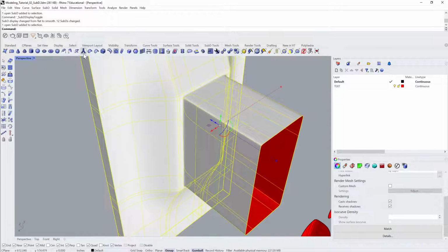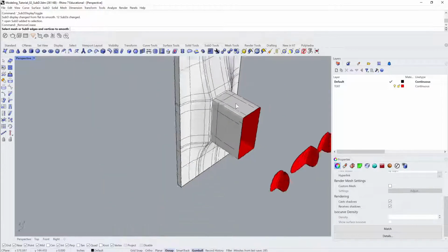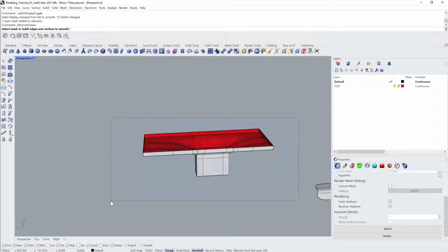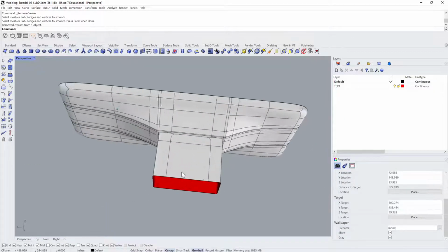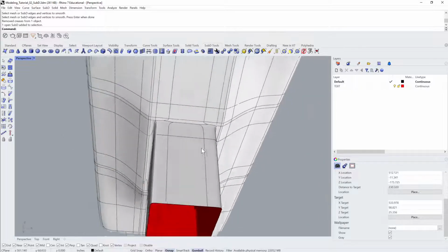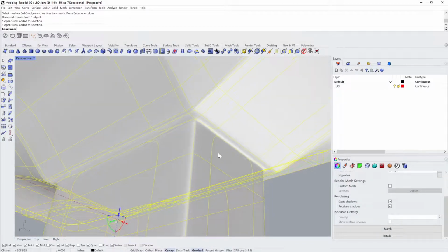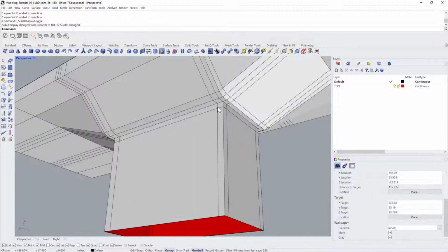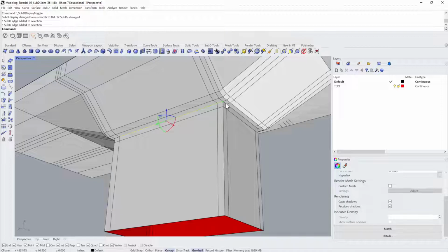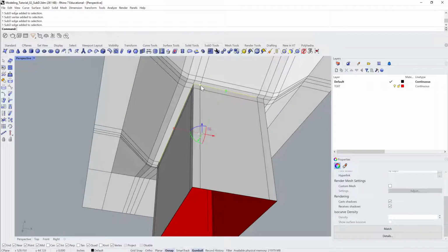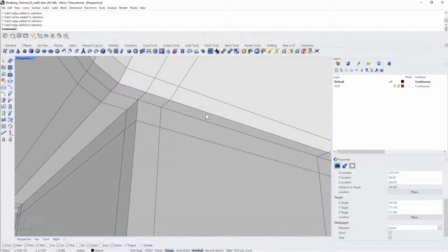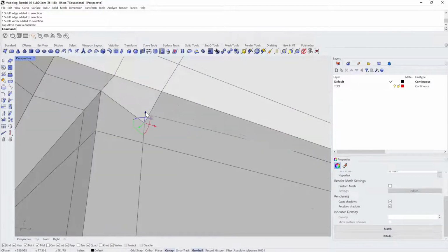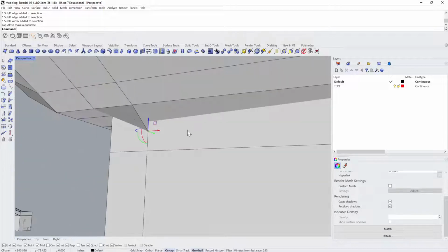And let me just remove, there might be some creases on this. Where am I? Remove all creases. Maybe that helped a little bit. Or maybe what I simply need to do is, it could be that these vertices aren't merged, but they look, that's the problem.